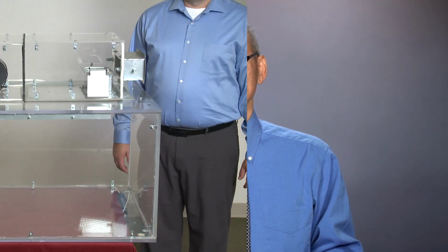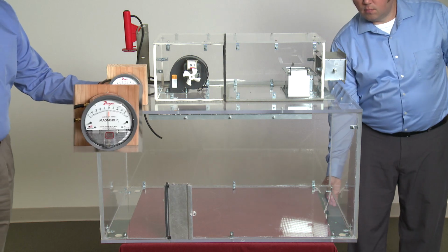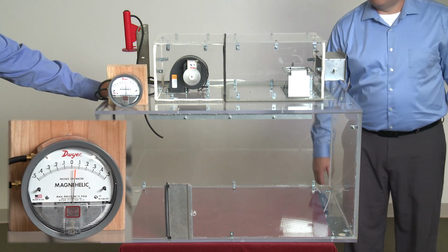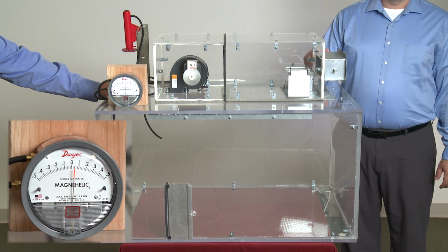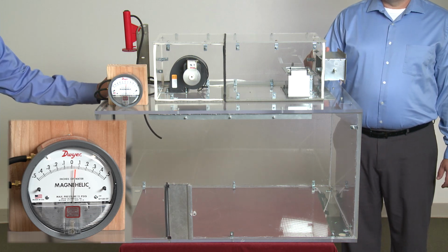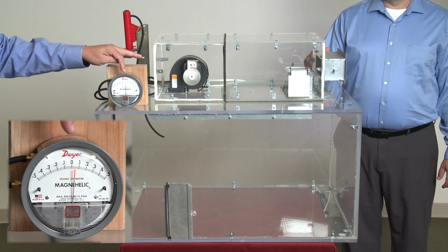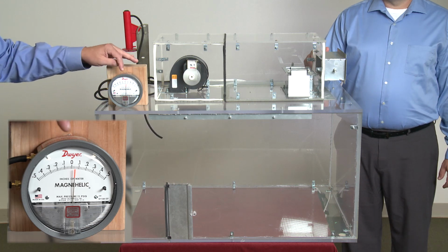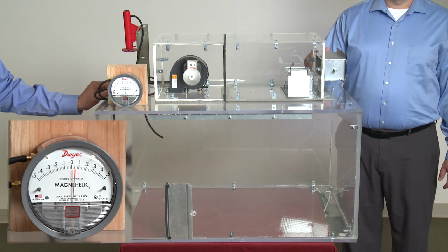John and Eric, can you demonstrate how natural relief works? To demonstrate natural relief, we'll first turn on the supply fan. Right now, Eric has the return air damper fully open and the outdoor air damper fully closed. So this is recirculating only mode, such as maybe during morning warm-up. With air just recirculating and no outdoor airflow being brought in, the difference between the indoor and outdoor pressure should be 0 or neutral. But you see that the needle reads just a bit positive, probably because the outdoor damper is not leak tight.